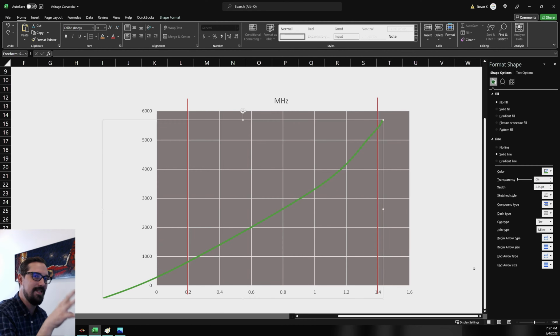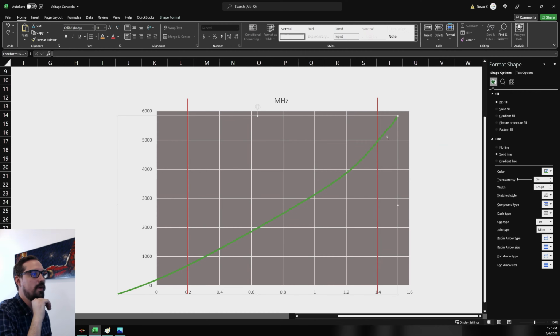Now this chart is a representation of the curve. I don't know what the exact curve settings are that AMD has built into the CPU, but when I look at where the stability issues can come in, it's actually in the lower range of your megahertz. So sure, at peak load, my CPU no problem will run 5 gigahertz, but I run into stability issues when the clock speeds are lower, or when they're lower down in the voltage range, because now there is not sufficient voltage to actually maintain the clock speeds required at the lower clock speed levels.